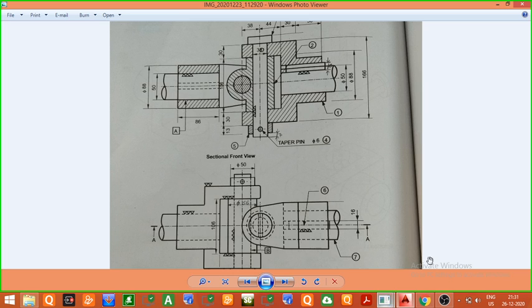Now in the next step, if I observe this figure from the top view, this corner point will not be visible. These two corners, this corner and this corner, were on the outside. So if we observe from the top, both of these corners will be visible. But this corner will not be visible from the top, because above it a plane surface lies. So this corner point is lying below this surface, and from the top view this corner will not be visible.